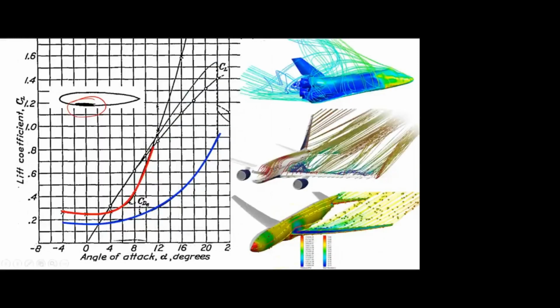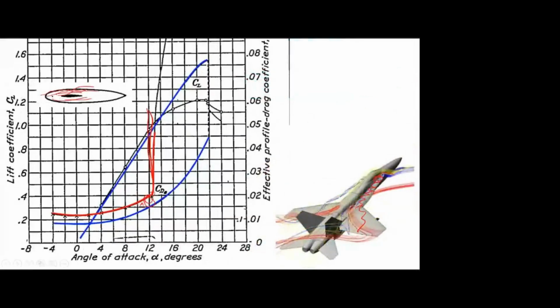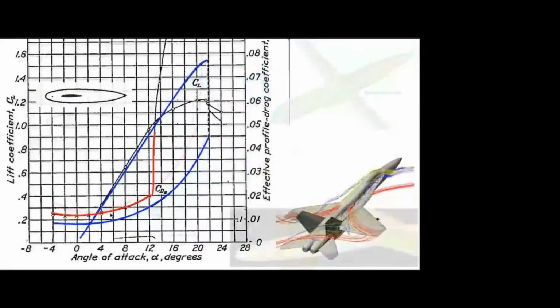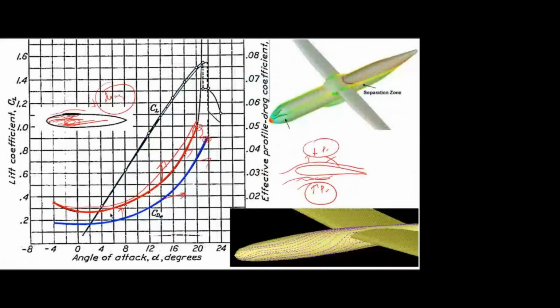And if you go for the low wing, almost all the disturbed flow will be there on the upper surface. So here you can see from 6 degrees itself, the drag is increasing. Okay, at least in the mid wing, from 12 degrees the drag is increasing. Sorry, from 12 degrees the drag is increasing for the mid wing. For the low wing, from 6 degrees onwards, the drag is increasing. So now if you compare these three configurations, the high wing only produces minimum drag.